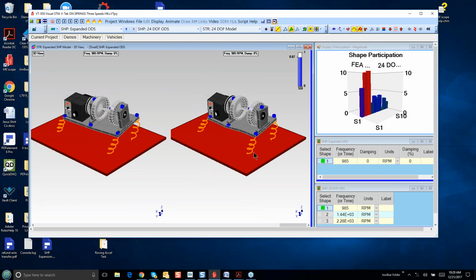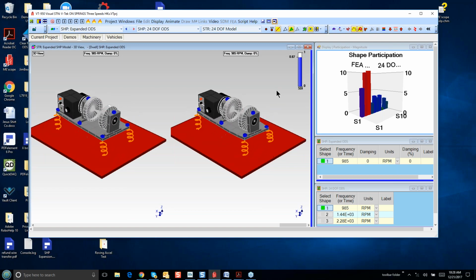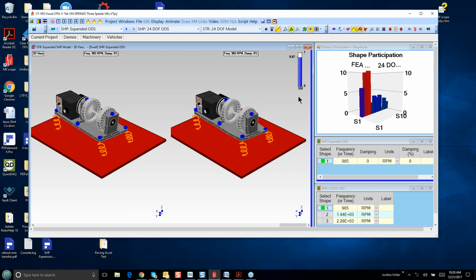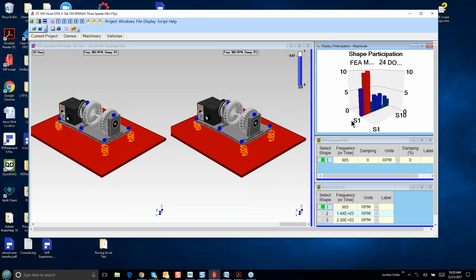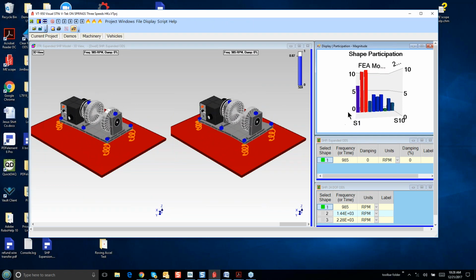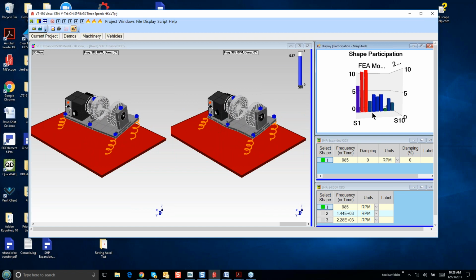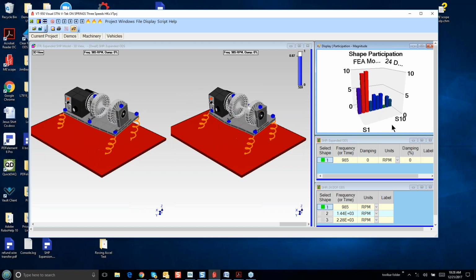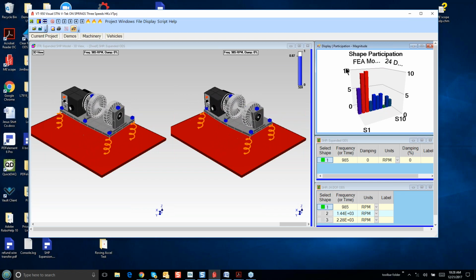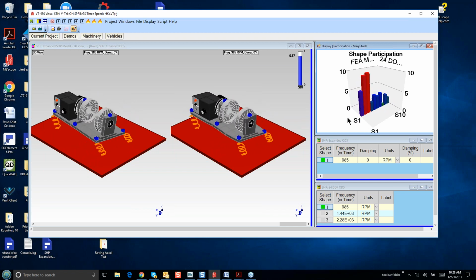So now we can see we're up to, well, 87%. Got a little better on the curve fit, or on the match between the expanded and the experimental. And we're still heavily using 2 of the rigid body modes, but all the modes are being used in a different amount. These numbers are just the numbers in the participation matrix. They don't go between 0 and 1.